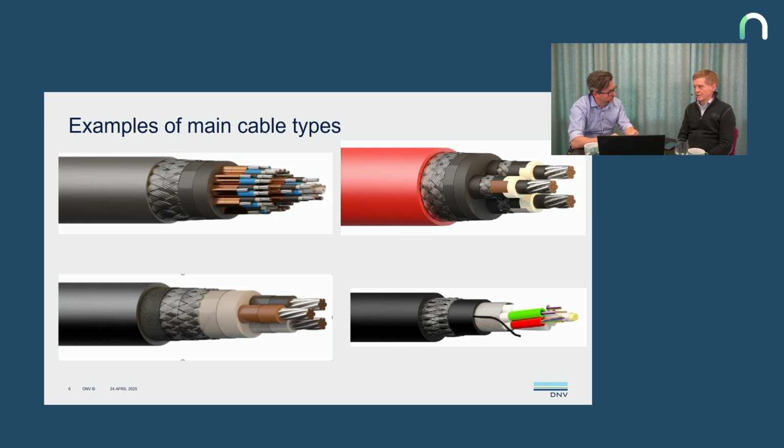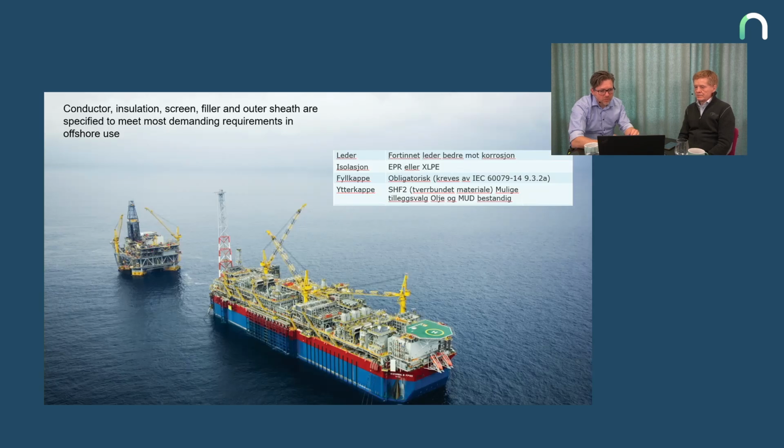There is a gas leakage test in this IEC 60079 part 14, isn't it? Yes, an annex there. So there's a certain requirement that the gas pressure shall not drop too quickly. Yes, because I'm not sure we can call it gas tight, but it's semi-gas tight, and it's better than a cable that's just put together without this extruded inner covering. Okay, we can move on a little bit.